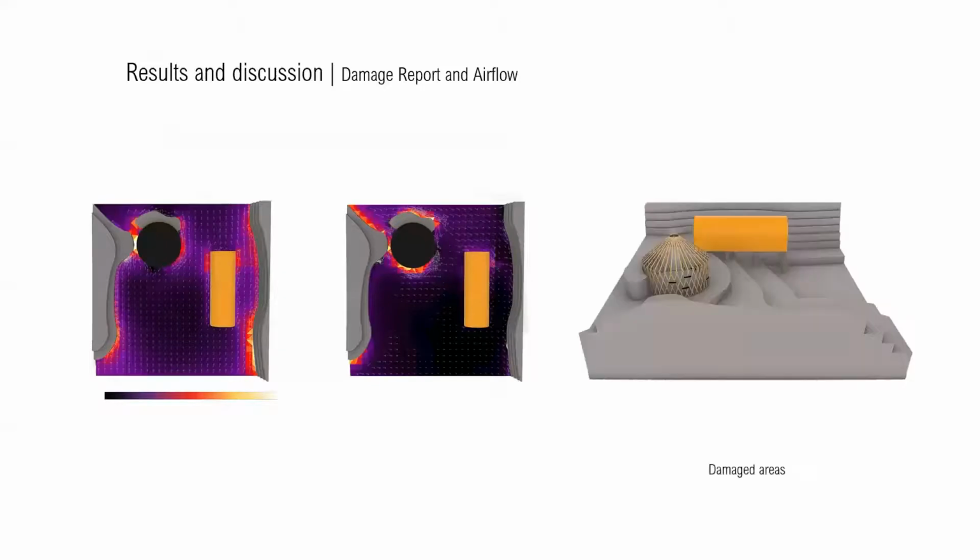Results from the northern and eastern wind analyses showed higher values in the damaged areas due to the constrictions created by the shelter's cylindrical geometry, the terrain near the eastern side, and the permanent refuge in Collins Bay on the western side. Moreover, the speed heat and vector maps show a clear relation of high speeds and constricted areas with damaged zones in the structure.